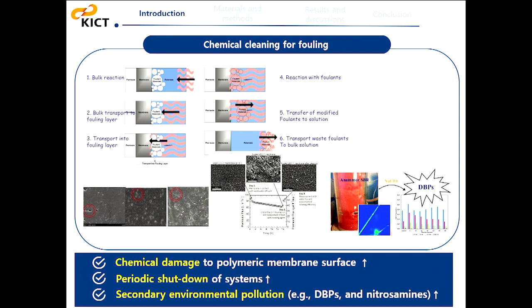Because of protection provided by the EPS matrix, biofilms have strong resistance to chemical penetration and hydraulic cleaning cycles. Bacteria reportedly produce more EPS under these kinds of stressed conditions, thus requiring excessive cleaning agents to control biofouling in reverse osmosis membranes, which leads to secondary environmental pollution. In addition, polyamide membranes inevitably degrade during chlorine-based cleaning cycles and require more frequent replacement.